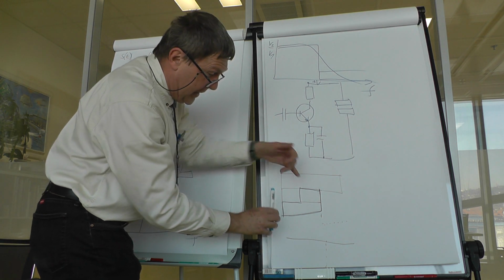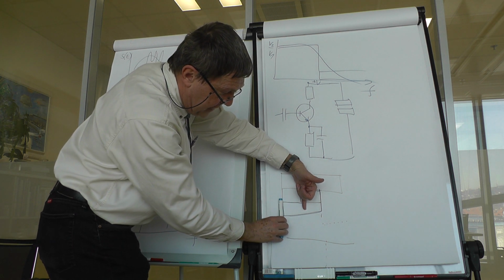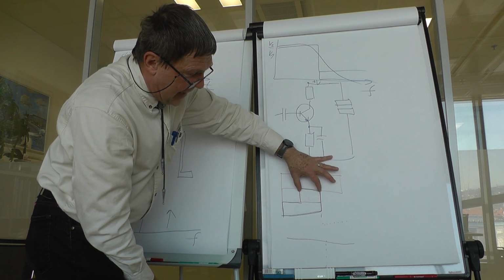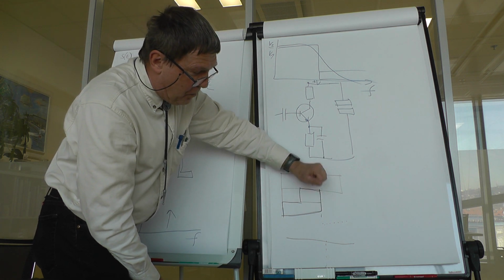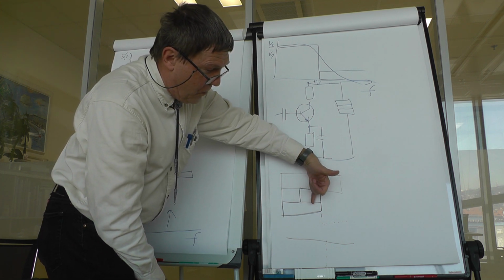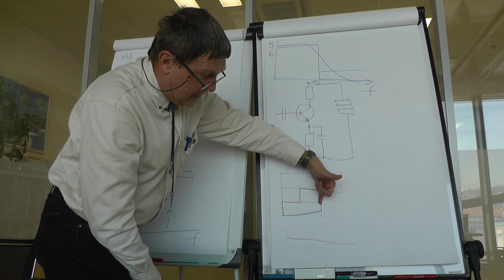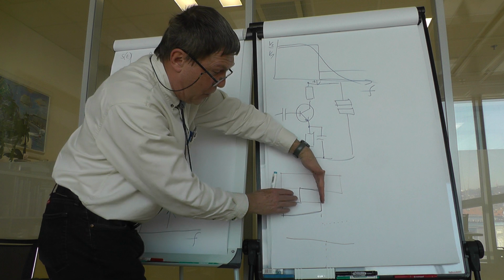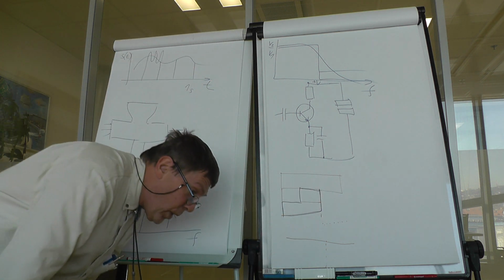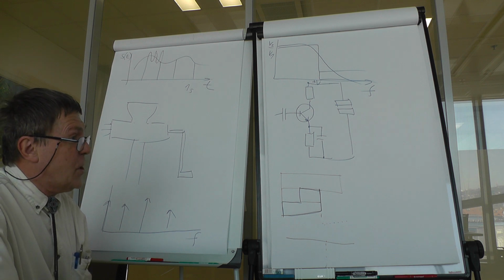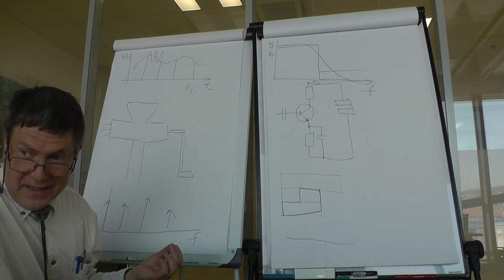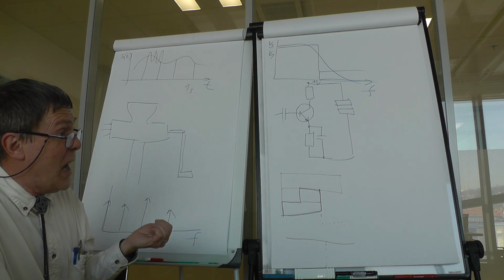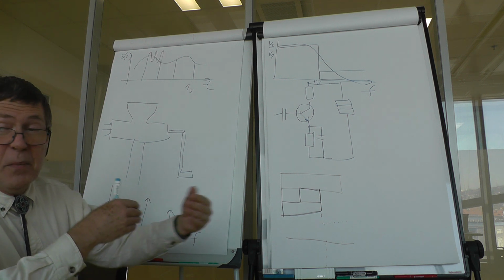you will get correctly the frequency content from 0 to 100 Hertz. And then you would get mixed the frequency components which belong to 100 to 200 Hertz and those that belong to 200 to 300 Hertz. So you get a scrambled signal which is difficult to interpret, first, and second, that information would be mixed and you have no way to decode it back.